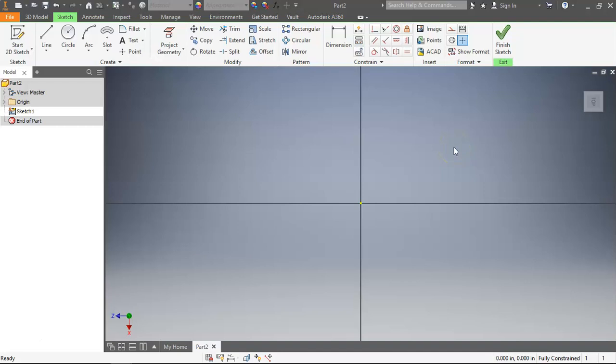And before we draw the part, I just want to have a quick little demo on what constraints are. I said before that you've done them before without even knowing it. Here's what I mean. When you drew a straight line, that little constraint that comes up right here in that little space where our mouse is, that is showing, okay, this is going to be a 0-degree angle. If you do 90 degrees to that angle, that little perpendicular constraint appears, saying that those two lines are going to be 90 degrees from each other. You can't change it, right? I can't move this angle up or down. I have to move everything because it's locked at a perpendicular line. If I just did an unconstrained line, I 100% can move it any way I want because it's not locked.